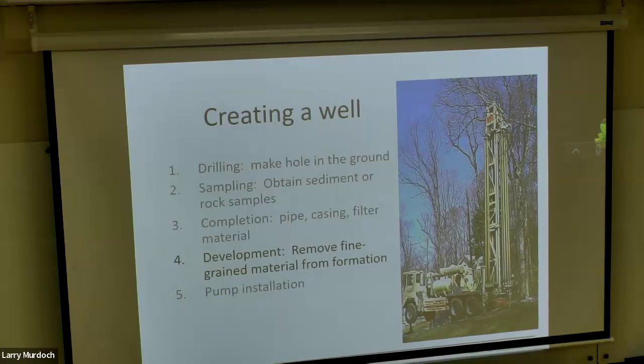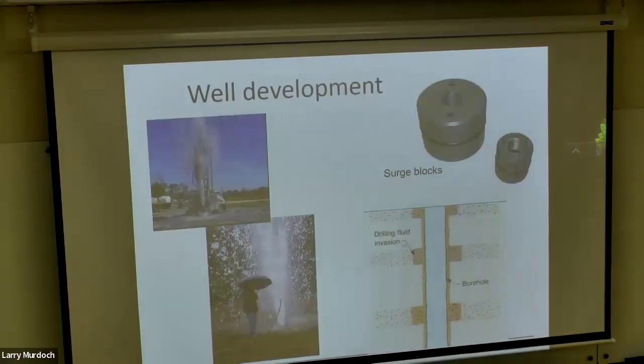So now, getting into a little bit of the detail of what I was showing there. In order to get this well to work, we need to, in many cases, develop it. The simplest way that a lot of drillers do it is they just put a pump in the well and pump water out until it comes out clear. That doesn't really mobilize fine grained materials that are stuck onto the formation.